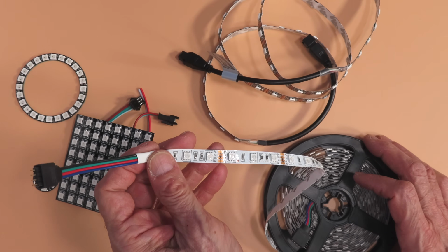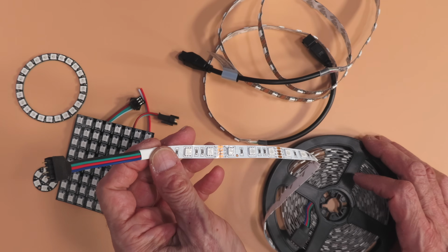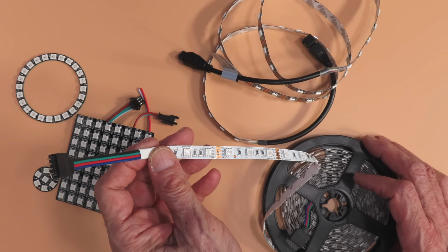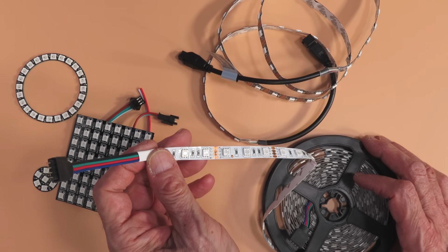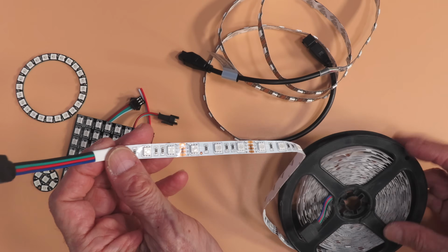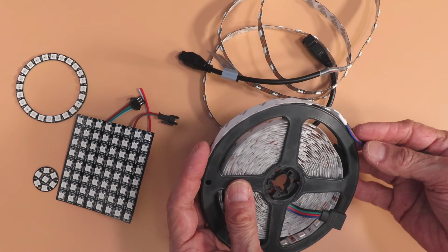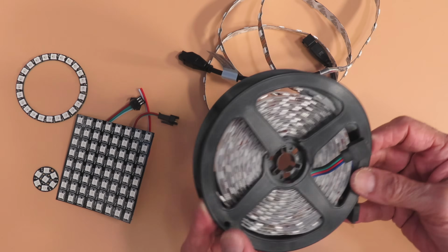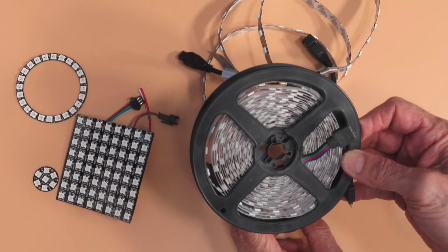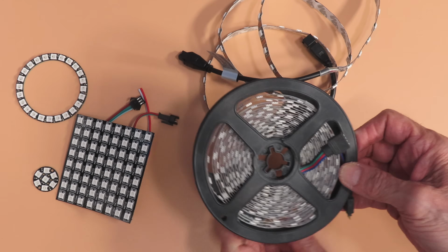And this, of course, can be driven by WLED, but you need a different hookup. You need MOSFETs in the hookup because it has to be able to handle the current of all the LEDs on the strip. And this, by the way, is the way a lot of strips are packaged. They're packaged in reels, and so they're very convenient. You can buy a bunch of these things and store them quite easily.